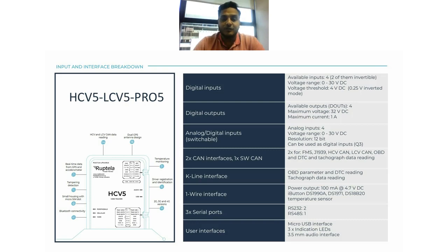In case the RS-232 accessory that you intend to use is not supported, we have an option called transparent channel, which basically dumps all the data that is being received from the accessory on the RS-232 port. If you have a specific data requirement from that accessory, you can filter that particular data using the start and ending symbols, and all the data in between the start and end symbols will be directed towards the server. So if you could do some changes on your server, you can have an accessory that works on RS-232 without firmware changes of the device.